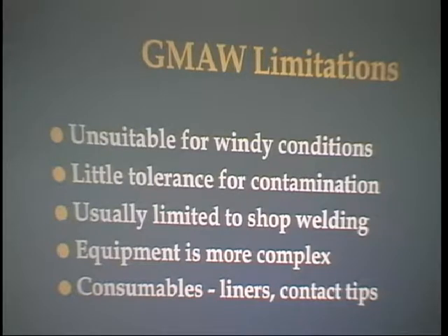You should be cleaning your parent metal, cleaning all the rust off of it, all the oxides off of it, all the mill scale off of it before you weld. Take it down to clean white metal. It's usually limited to shop welding, and actually about 70% of the shop welding done in the United States is done using the gas metal arc welding process. The equipment is somewhat complex, and then you have other consumables besides the filler metal and gas, consumables such as liners and contact tips. Those things will get used up after a while, and they have to be replaced.